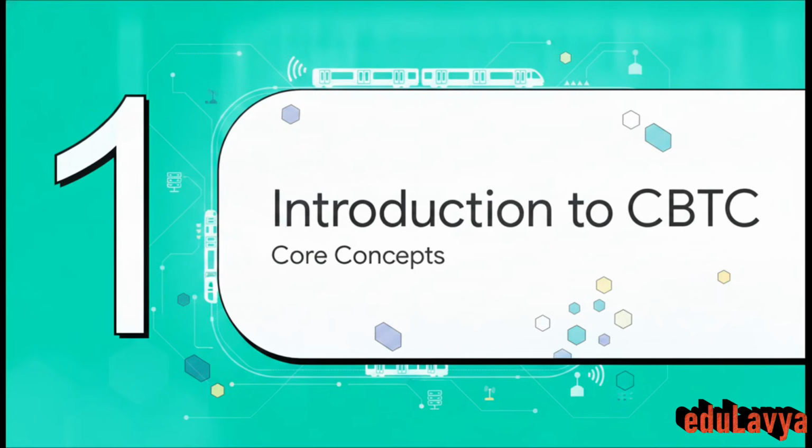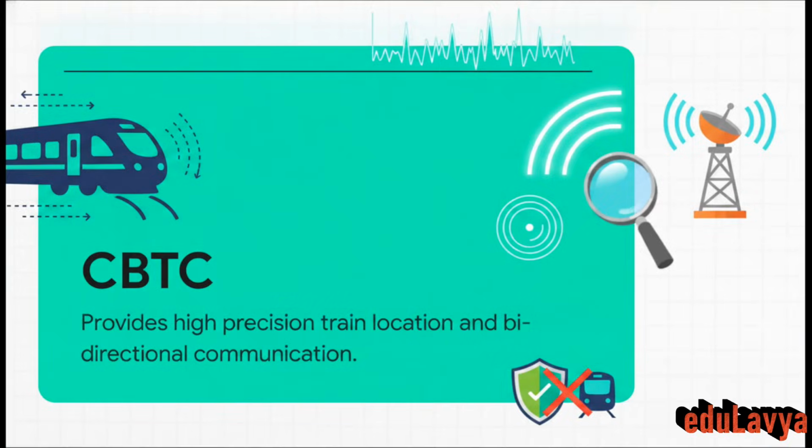All right, Section 1, Introduction to CBTC, Core Concepts. So what actually is CBTC at its core? Well, unlike those older, clunky systems, CBTC gives us high-precision train location tracking that is completely independent of traditional track circuits. It relies entirely on this continuous, high-speed, two-way communication between the train and the wayside. And why do we do all this real-time data exchange? Simple: absolute safety. We're talking about utterly eliminating collisions and literally preventing any train from physically going over its speed